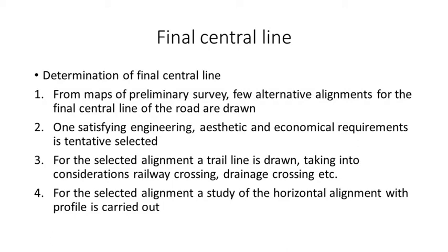Okay. In the preliminary survey, we select the primary traverse, then topographical features, then leveling works, then drainage studies and hydrological data, then soil survey, then material survey, and the traffic studies. Okay. Again, we require to collect data in the survey on the character of that embankment foundation. What is the character of that embankment foundation? Next, what is the construction problem? Either there is high level water storage, there may be a landslide problem, there may be a slope settlement problem. So what construction problems occur in that particular area? Soil problems, we also have to find out.